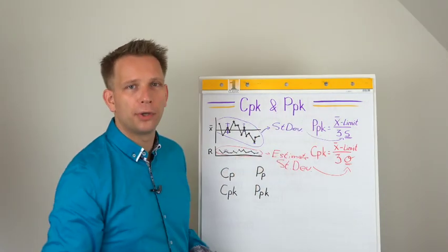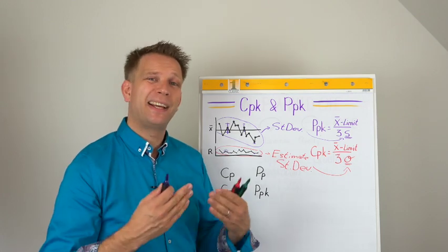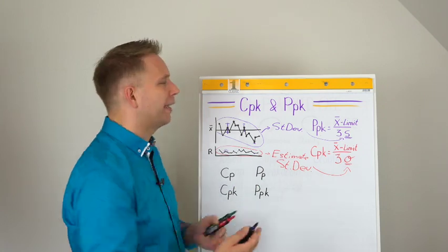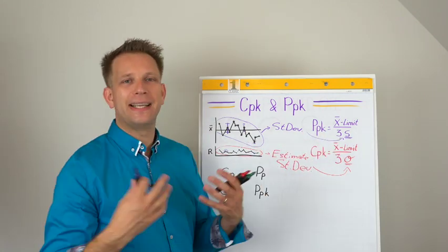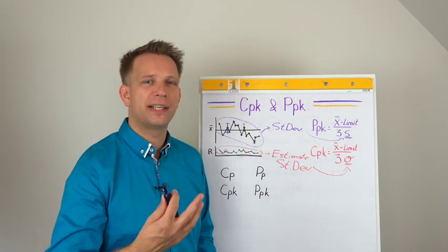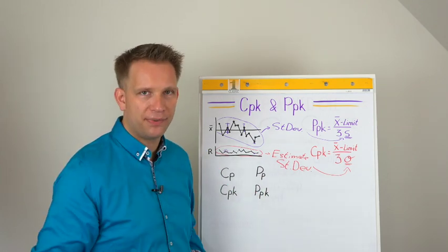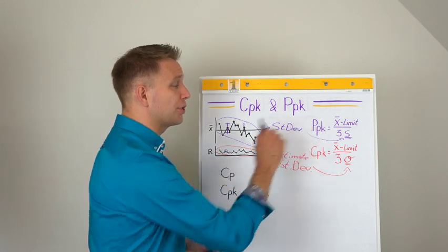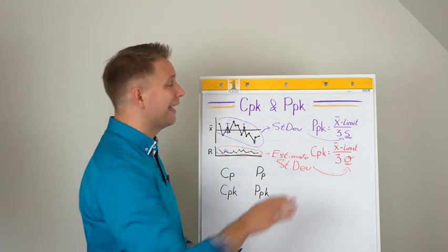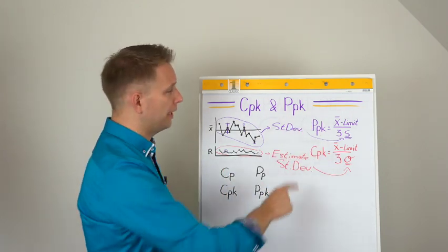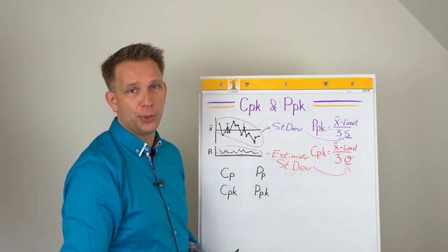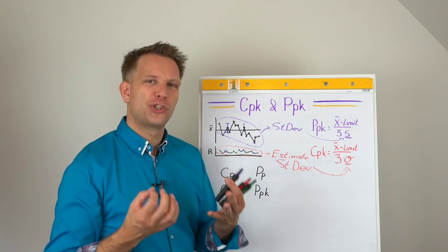Some clients will want the Ppk because if they are getting quite a lot of batches from you, they would also like to know that your whole product is nice and stable and that each batch that they're getting is again the same as previous ones. For your internal quality control system, this of course is a very good indicator. In fact, if you have to choose within your company, take the Ppk because that tells you how your whole process is doing and gives you, let's say, the strictest number.